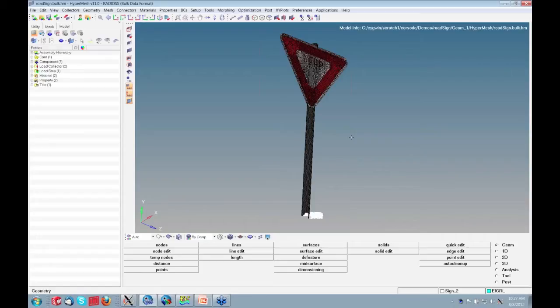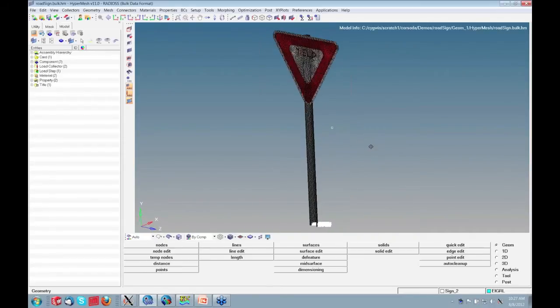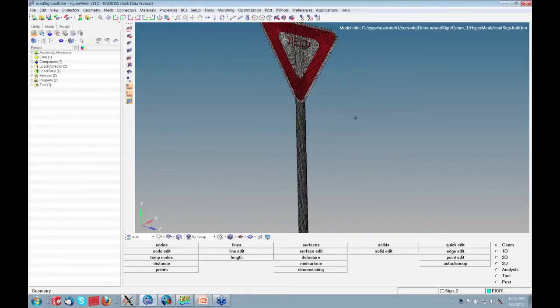And then we're going to set up our simulation to compute the first, I think, 20 modes is all I set this up for. And there is no limit on the number of modes that we can include when we're doing this analysis using AcuSolve. We can include as many as we want. For the most part, there's no need to include more than, say, 10 or 20 modes. Most of the energy is associated with those lower modes. So again, there's no limit, but for this application, I just arbitrarily chose 20.